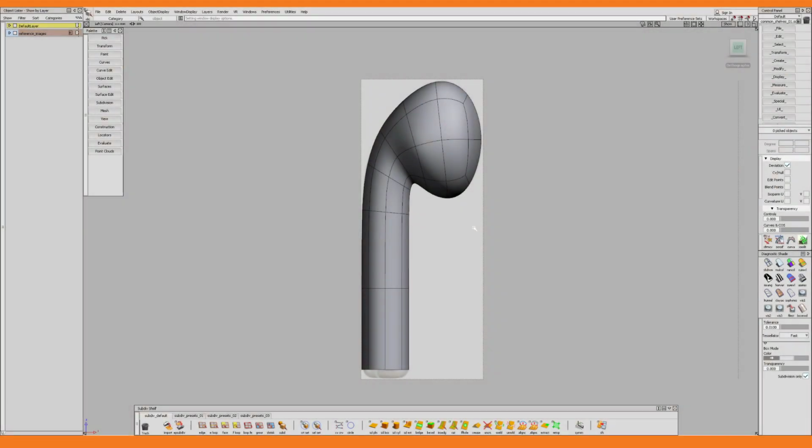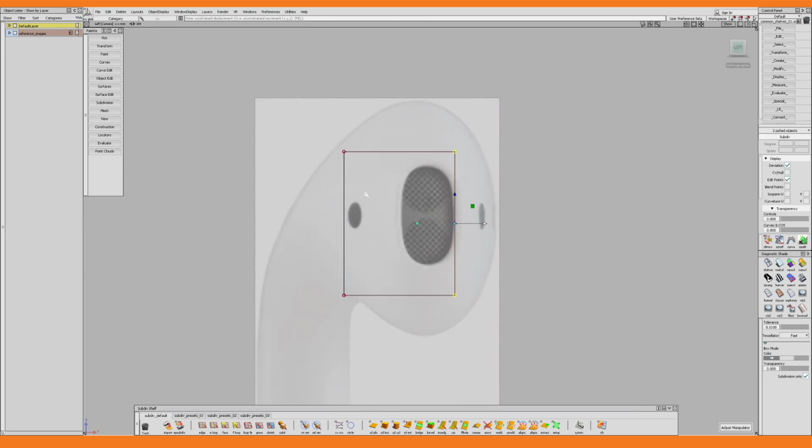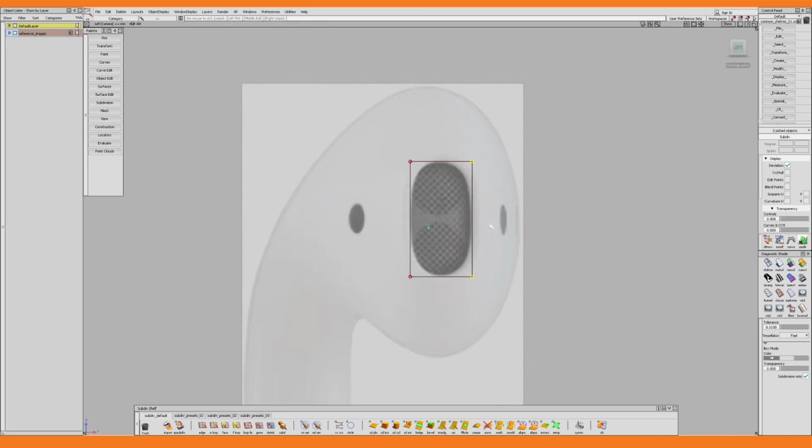For this, we don't really need the main volume, so I hide it using the invisible function. Then I start out by creating a plane, which obviously is way too big, why I need to scale it, as well as moving it into place. With the offset mode set to relative in the insert edge loop tool options, I then use the slider to insert edge loops with even spacing in between them.